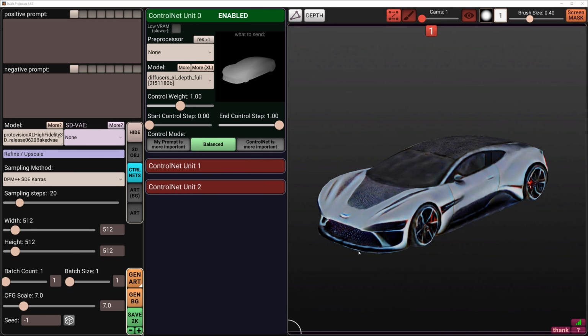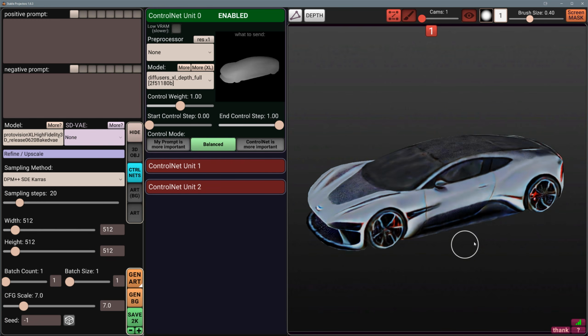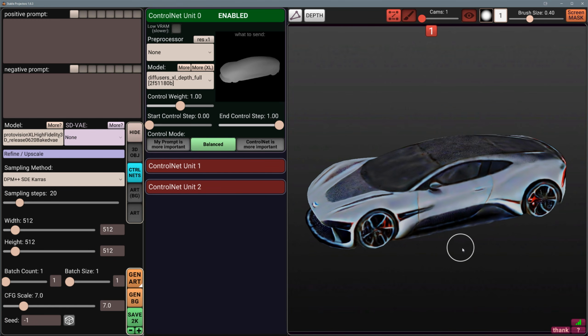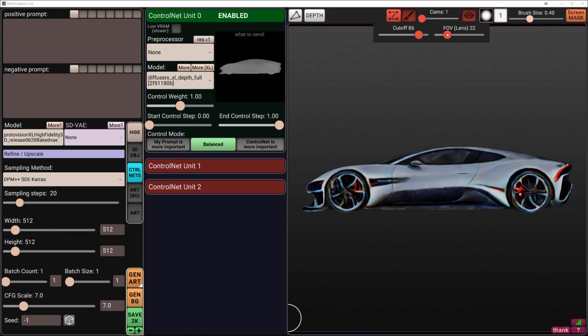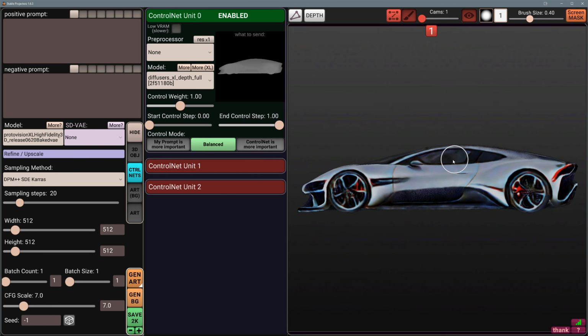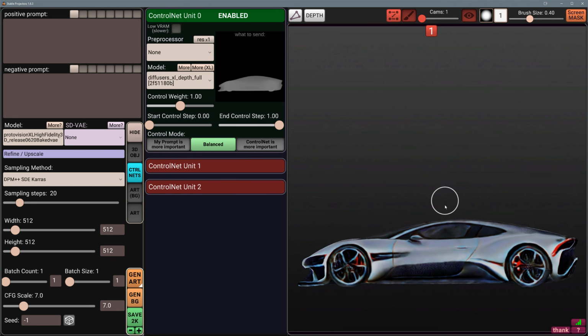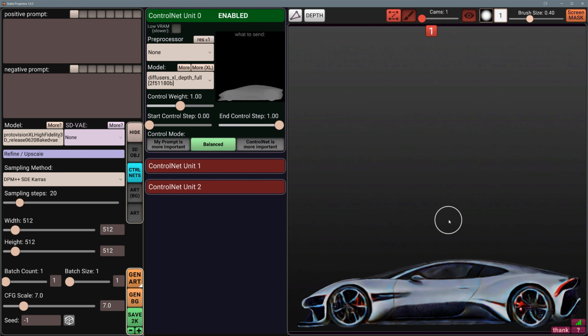The next thing we'll want to do is set up our workspace here, or the cameras, the layout that we want the model to be set up on, and the different angles we want textures projected from. So if you come into your 3D space, hit Alt left mouse button, you'll be able to rotate it around. If you hold down Control, it will snap to different views, and if you come over here to camera and you hover, you'll have your focal length here, which I will slide all the way to the left. This is more of an orthographic projection, which will be good for this side view. And then I'll just drag this down here and kind of fill the space.